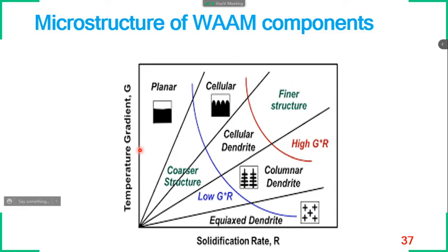Heat dissipation will take place generally only through the side walls, because once we pour molten metal into the mold, the side wall acts as a heat dissipation agent and can quickly extract the heat. So the heat dissipation is faster. That is how heat dissipation takes place in casting. But in additive manufacturing, it is not possible to easily predict how the heat dissipation will take place, since it is a transient heat source.